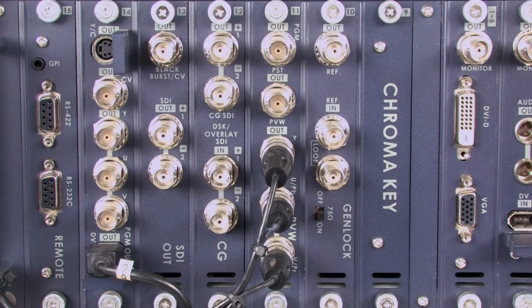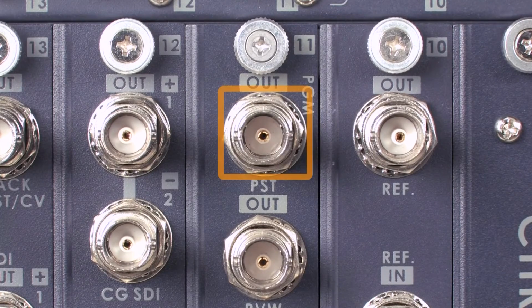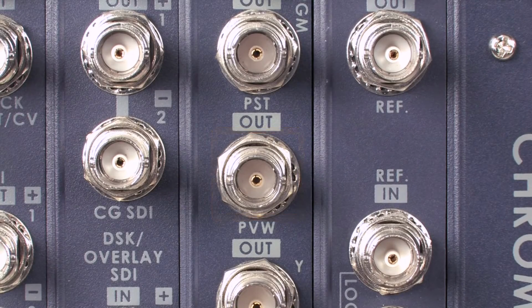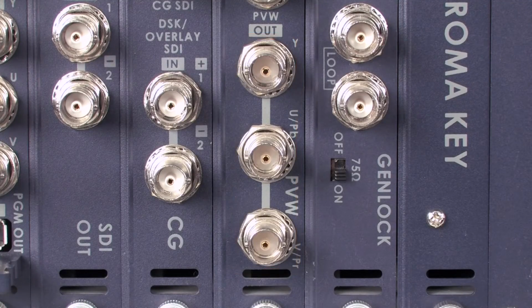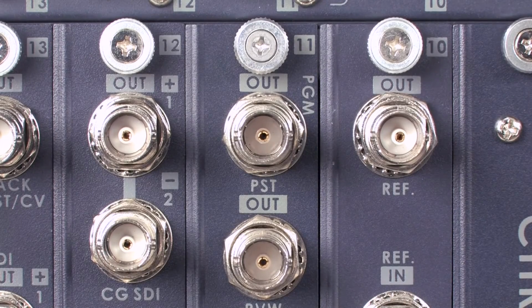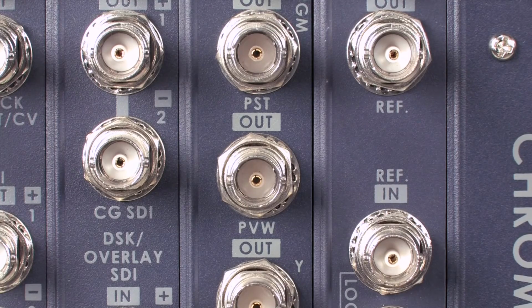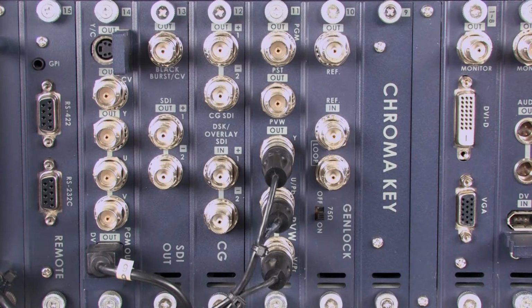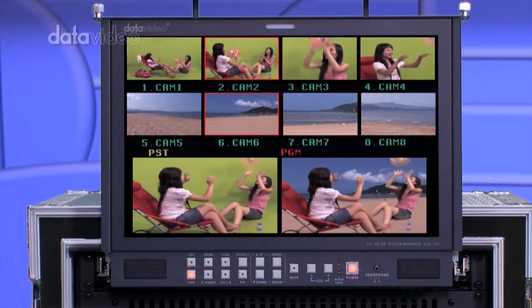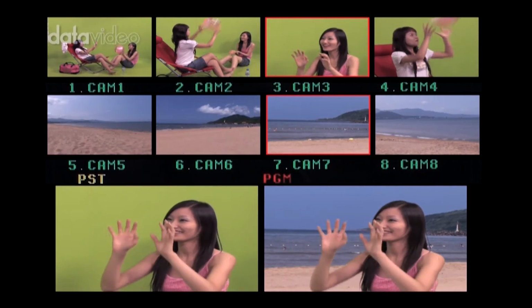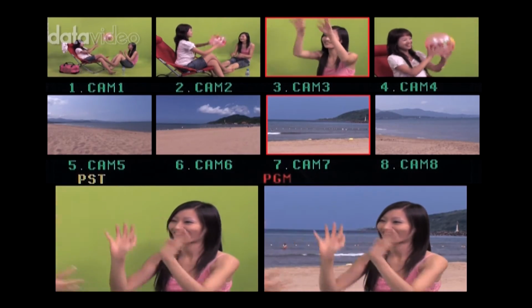If you buy an MS-900 and use a multi-image output card, you will notice that the card has a total of 5 output interfaces. From top to bottom: main output interface, preview output interface, and multi-image output interface, of which the main output and preview output interface connect to a single standard PC monitor for viewing. The multi-image preview output interface connects to the TLM170 monitor for monitoring a total of 10 videos: 8 input sources, as well as program and next source output.